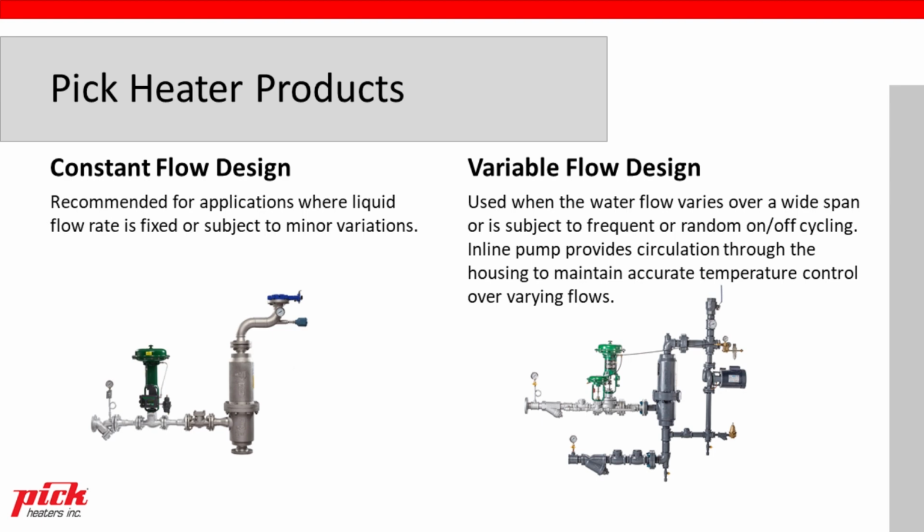And this design has an inline pump that provides circulation through the housing, and that maintains very accurate temperature control over those varying flow rates. So that's a little more equipment to the device, but still offering all the advantages of steam injection, including accurate temperature control.